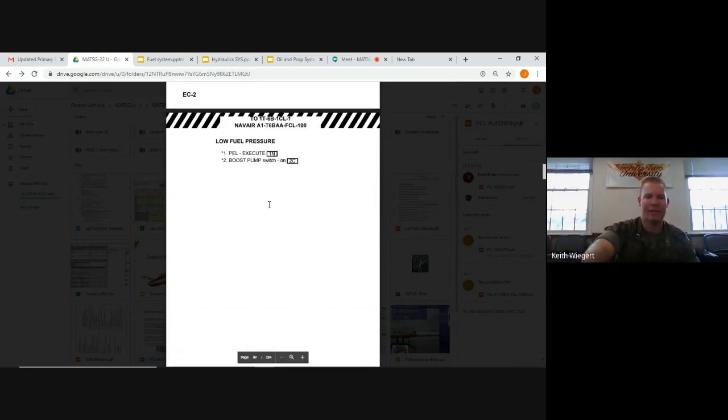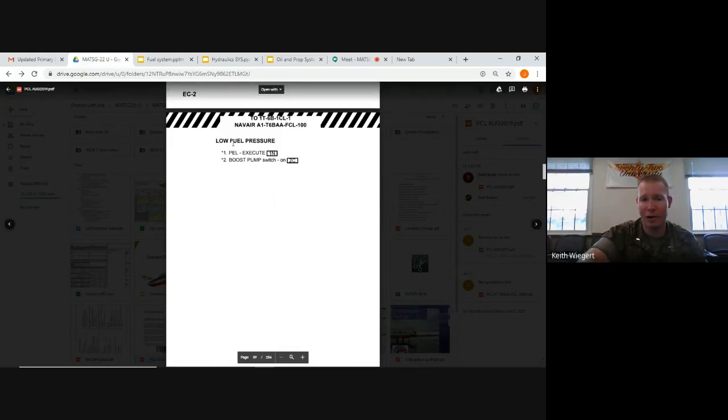All right, so let's talk about the CP real fast. Low fuel pressure. What's that going to look like to you? You're going to get a fuel PX warning that's going to pop up on your ICAS display, right? That means you've got low fuel pressure, right? All right, cool. The first thing we're going to do is PEL execute, turn, climb, clean, right?